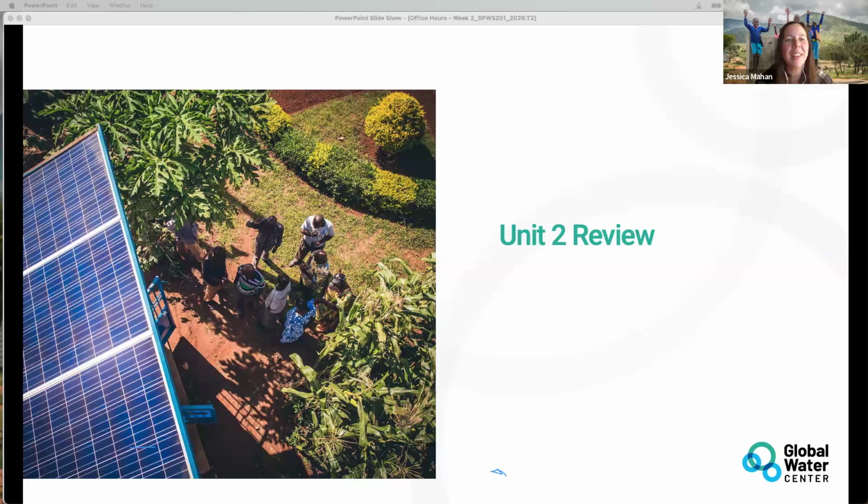Yeah, thanks. Those are good comments. You're right that a longer pump test, like 24-hour or even 72-hour, if you can do it, is a great option because it's going to give you a more realistic look at what your long-term abstraction can be safely. There have been situations, though, depending on how remote the well might be and what the safety considerations are around there, where doing maybe an overnight pump test just doesn't feel like a good option, or maybe, like you said, the budget just isn't there to staff it for that long.